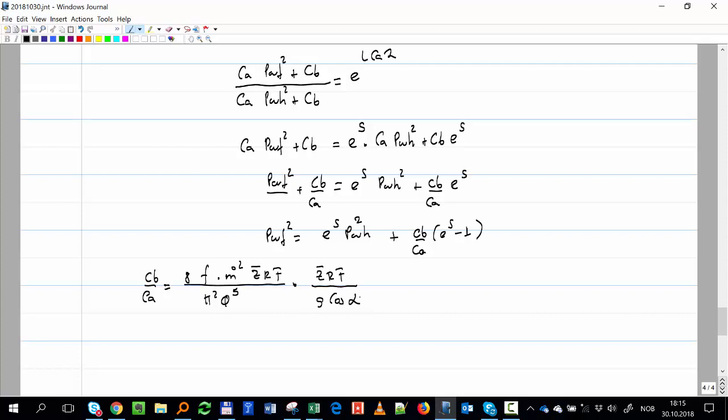Okay, I have pressure at the bottom, I have pressure at the wellhead, I have a factor S that I can calculate, right? So now in this equation, I need rate. Okay, and rate comes when I make the division between these two. You see here appears the mass flow. And the mass flow we learned last class that it can be associated with the standard condition rate, right?